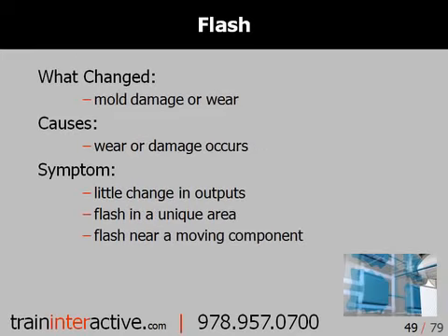If mold damage and wear happen to be the culprit, then you'd see flash in a particular spot in the mold. This would come up repeatedly, and this defect is most often the cause of when you're getting flash in a short shot.